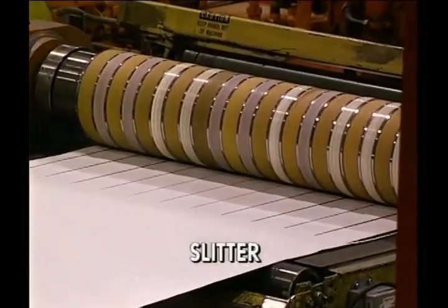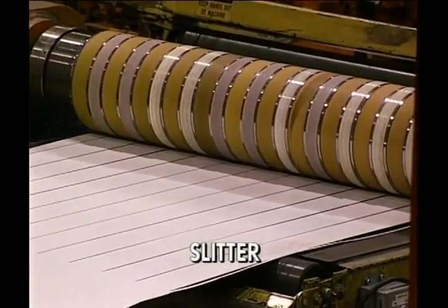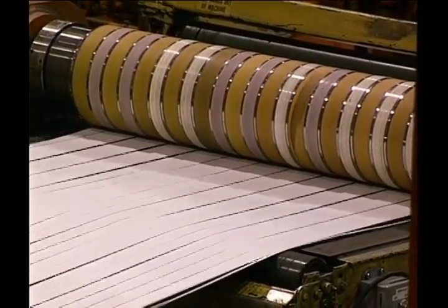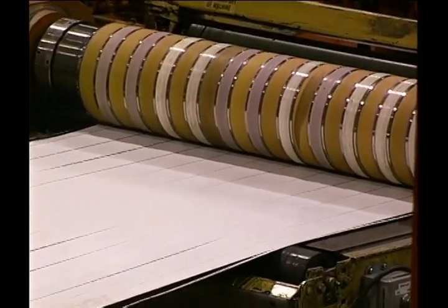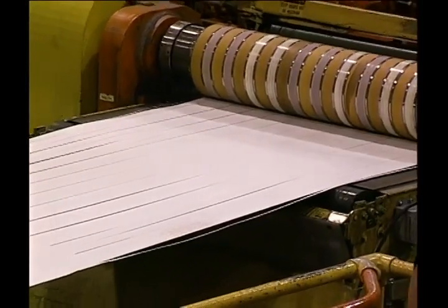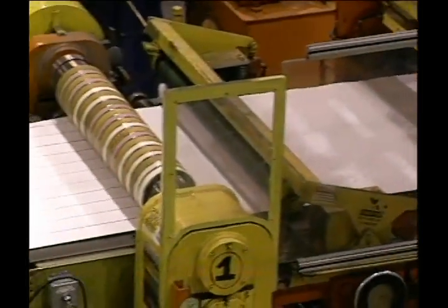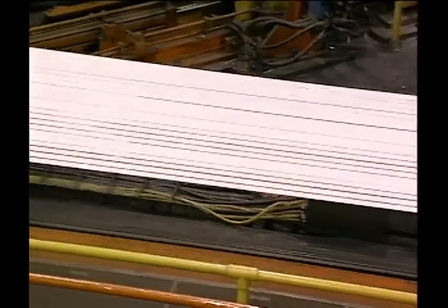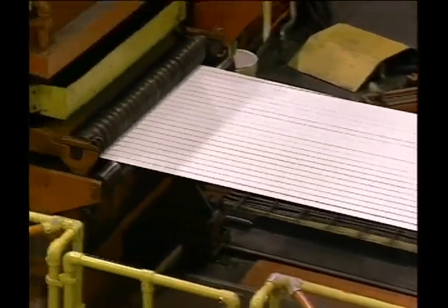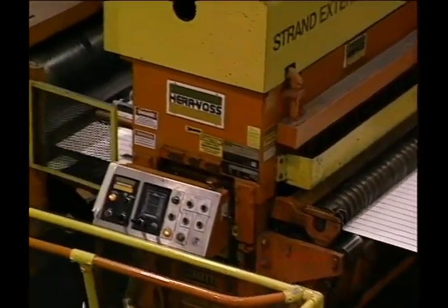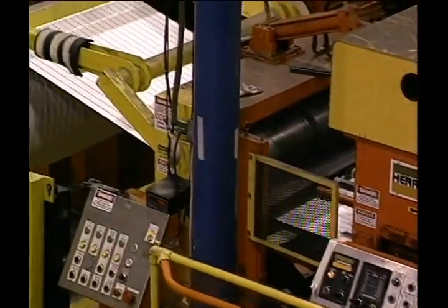The slitter holds parallel shafts containing rotary cutting knives. The material to be slit passes between these knives for a continuous shear. Since most master coils are crowned or bowed in the center, the processed center coils wind to a larger outer diameter than the end coils. The result is that the center coils pull tight as the end coils hang down loose.